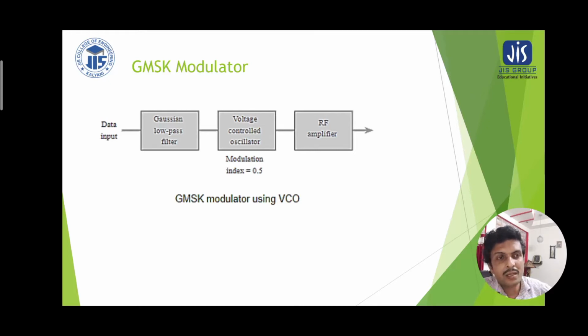That is why a gradual increase or decrease of magnitude may produce a carrier frequency which is gradually shifting from one frequency to another. Therefore, such a voltage controlled oscillator output signal will have many frequencies, and it will not produce any abrupt phase variation, and that is why the chances of noise in the output signal will be very less.